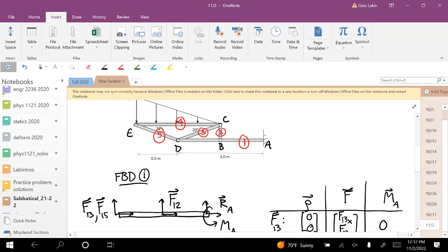And so you could treat all of those as cables that also have the ability to have a negative tension, and that's a way you could save some equations and some variables, and you get the same answer. You just know that because those are 2 force members, all of those forces have to act along the line between the 2 bodies. That just has to be the case.